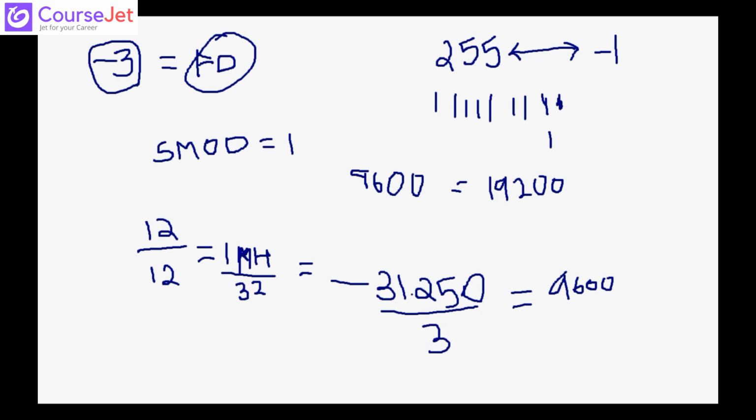Otherwise you can use any value depending on your data sheet, any value in between 1 megahertz, or even if you don't use a crystal oscillator and use even a switch, then also it will work properly, no problem. But generally we go for 1 megahertz to 24 megahertz, any value in between, depending on the data sheet.